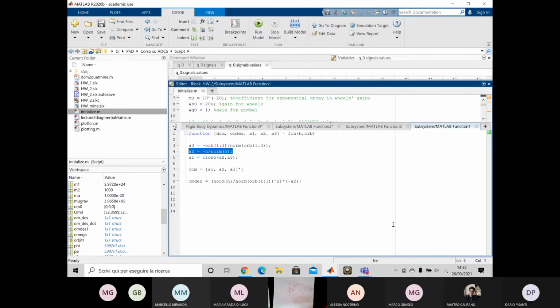In which case, the only other thing I could do is have the rotation Euler axis be 0, 0, minus 1, but I don't think it makes any difference, because in one case the rotation axis is pointing down but the angle is minus pi, and in the other case it's pointing up and the angle is pi. So what I'm trying to understand is whether I can obtain an orientation that has my body axes initially oriented like the ECI by rotating about this axis by an angle pi. And I think I can, because I take this and it becomes the one that points down, and I take this and it becomes the one that points that way. Though it doesn't seem to be exactly aligned with LVLH. You know what I'm saying?